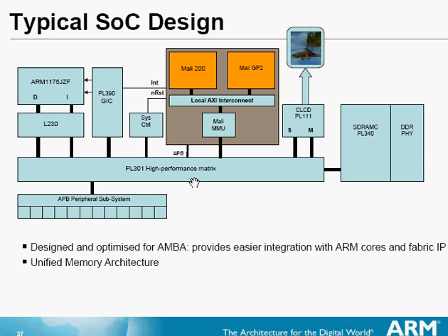You can see the connection here between the bus interconnect and the dynamic memory controller, which is an ARM PrimeCell peripheral, which controls some high speed DDR memory and maybe some PHYs to connect the physical medium like Ethernet or USB cable. PHY is the physical layer of the OSI model, an abstract description standard of computer network protocols and communications.